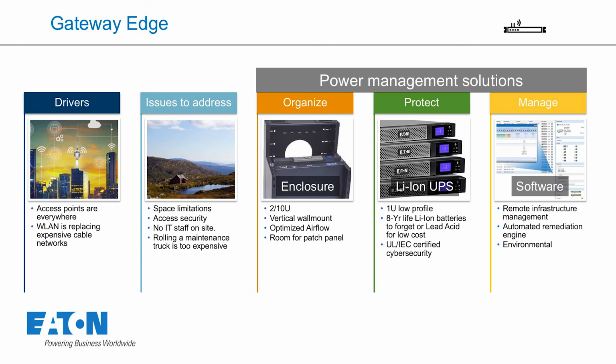There are accessories that go on the rack where the airflow can be smooth, where you reduce the amount of heat being generated because of all these cables being entangled with each other in back of the servers, and maybe you don't have an enclosed rack. So the accessories will help improve the temperature.